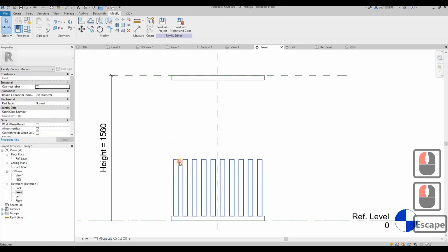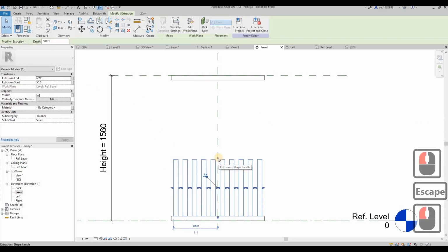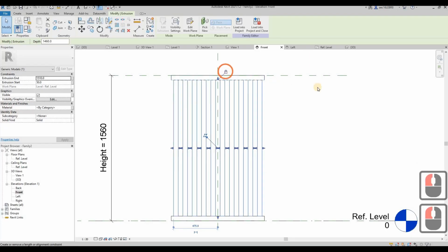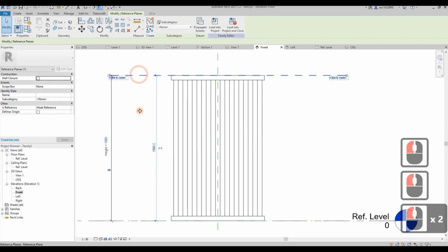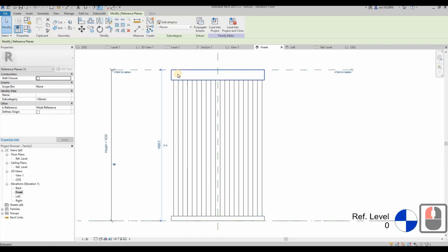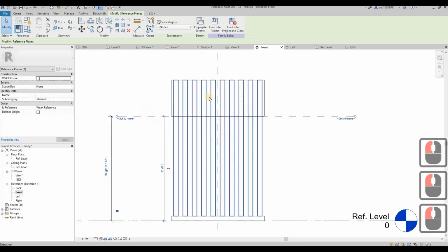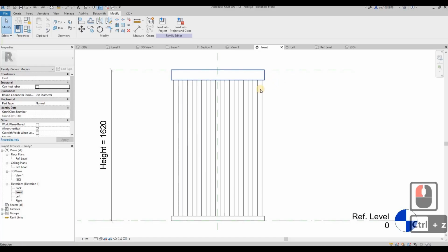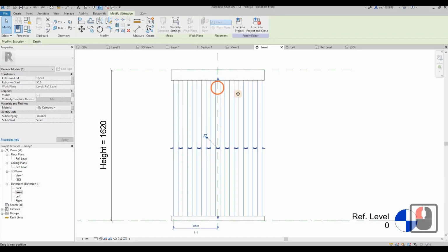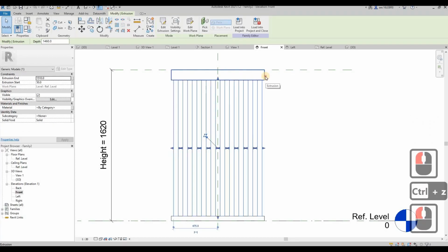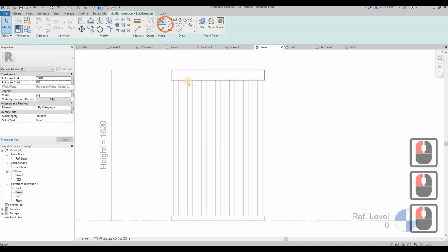Okay, so now I'm going to move these Louvres to here, then I lock this here. Okay, so now if I change this height, it will create some arrows over here because you see if I drag this, it is locked by these Louvres. Okay, so let's undo. So how are we going to solve this? We're going to detach it first, or if you cannot detach it, we're going to edit this extrusion.